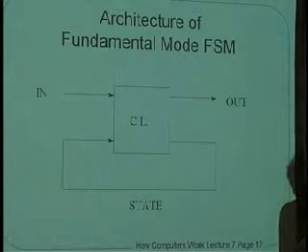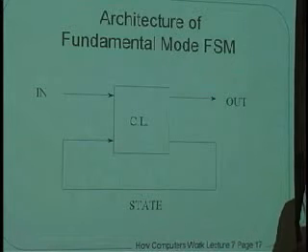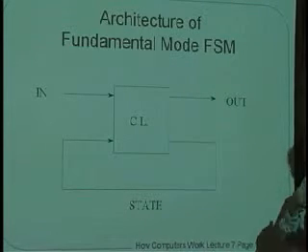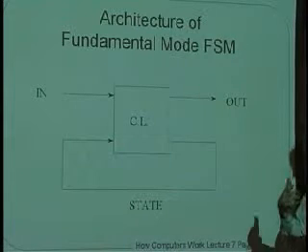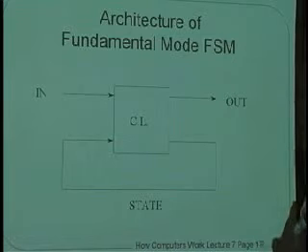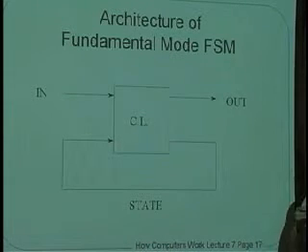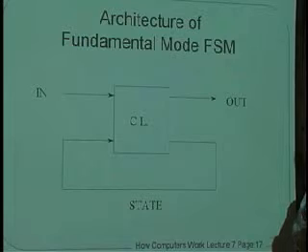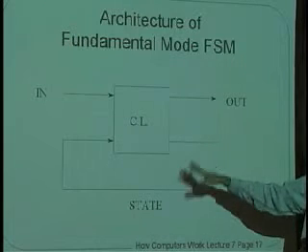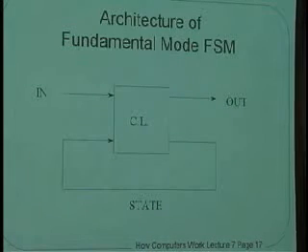And what went wrong on the blackboard was because we weren't at all being careful about how to time this thing. And what I hope you are getting a feeling for is that in this lecture we're being extremely careful about the exact timing of the signals that are going through here. We're considering contamination delay and propagation delay. We're considering hazards. We're looking at all the possible things that might go wrong in a circuit like this. Well, what's CL here? CL stands for combinational logic, same as before.